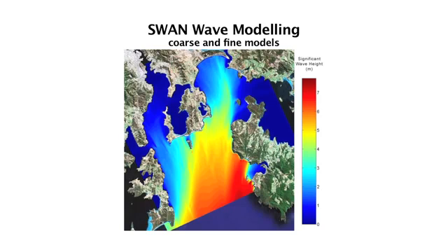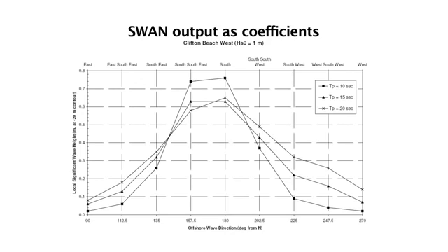It all looks nice and pretty as well, but to get a design wave height at a given location, we have to go a bit more black and white than that. So even though the other graphics look really pretty and look impressive, this is probably, for a raw engineering calculation, more what we need. So for a range of offshore wave directions, realise it's very direction sensitive. So this particular site, we've got wave directions going all the way from east out to west, and southerly waves are here. Now obviously that site looks pretty open to the south, if you saw.